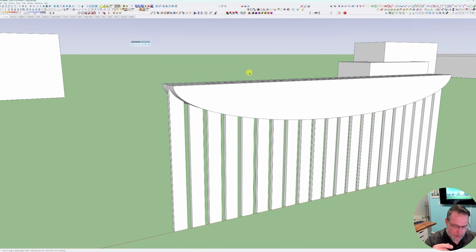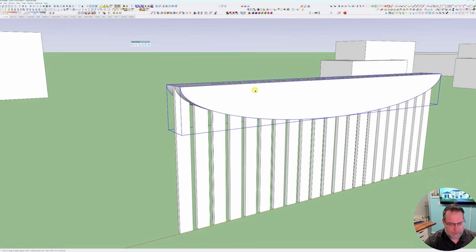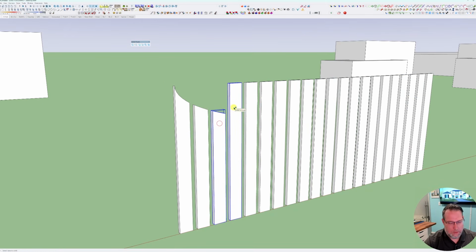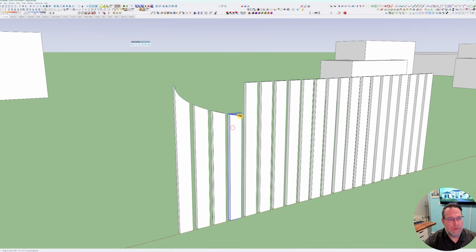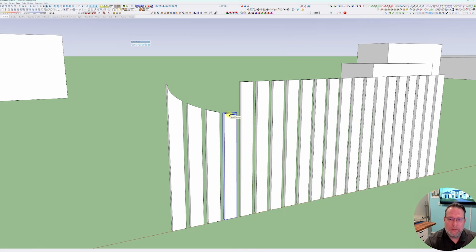And just to also add it out there, I use Alt V as in Victor as my subtract because I use subtract quite a bit. So if I select the first one, Alt V, second one, Control Shift V, select the first one, Alt V, subtract. So you can see I can continue to do this, but we're also always looking for efficiency. How can we be super efficient?